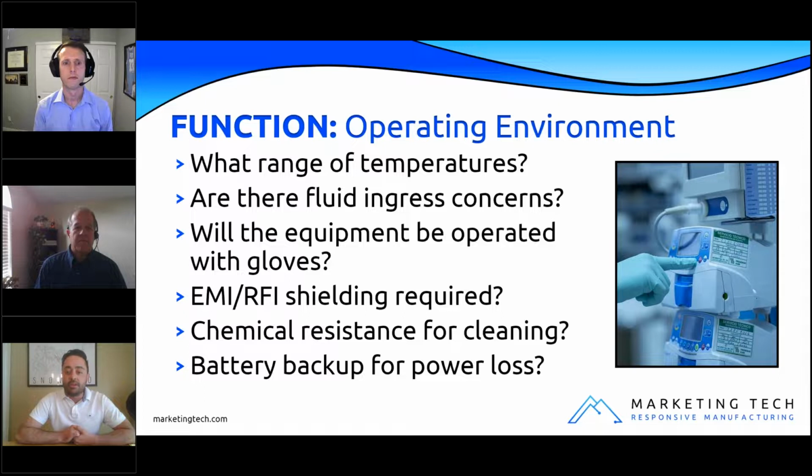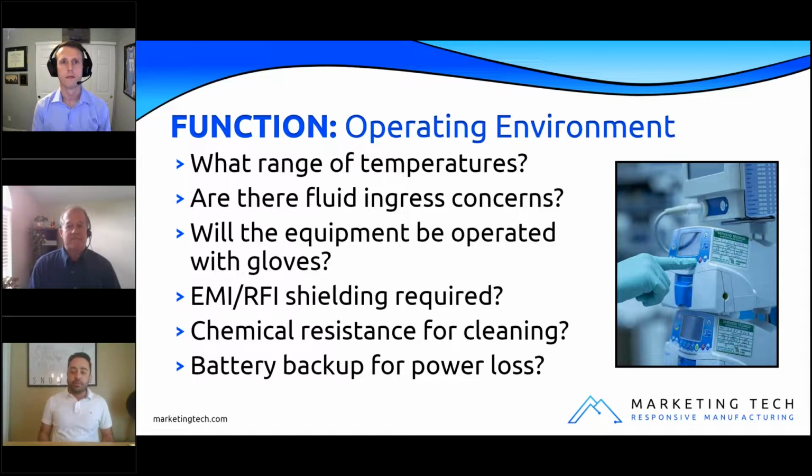Any EMI RFI shielding requirements, the chemical resistance for cleaning. So is your equipment going to be routinely cleaned, and the harsh chemical compounds that they use, that just should be considered when selecting the right materials. Is there a need for a battery backup? If this is a critical device that a power surge in a hospital could affect the performance of, maybe a battery backup makes sense.